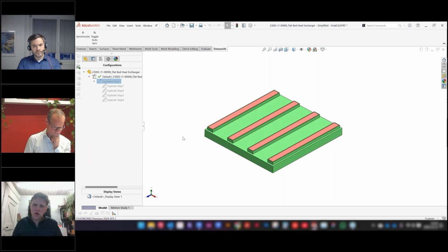It reduces the complexity of the computational processing power of the simulation. It means we get to either fail or succeed quicker, and it's a really great saving. I've seen a few variations of this type of simplification done on other projects by other companies. What we do differently here is that we've got these strips of represented volumes. It's really important that we maintain the same surface area of the fans throughout the simulation.